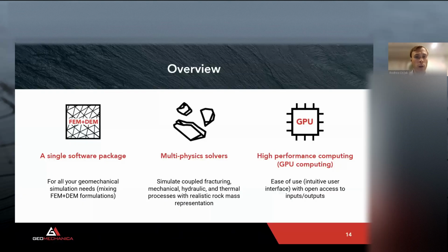A quick overview of the software. As I said, it is a single software package for all your geomechanical simulation needs in one tool, essentially, which mixes FEM, so standard finite element capabilities, with DEM capabilities. It is equipped with multi-physics solvers to simulate coupled mechanical, fracturing, hydraulic, and thermal processes with realistic rock mass representation in terms of explicit inclusion of discontinuity networks such as faults, joints, and bedding planes.